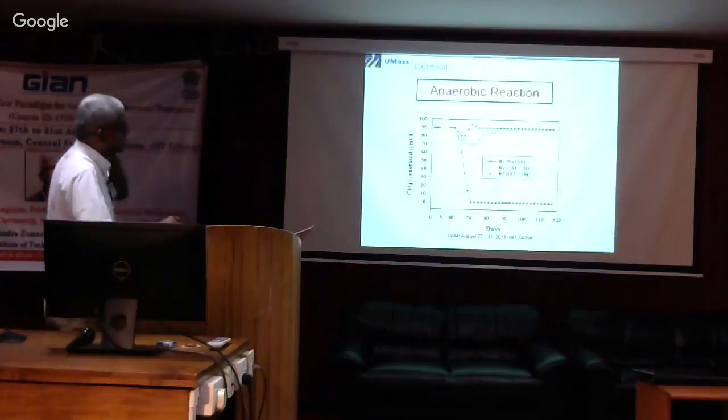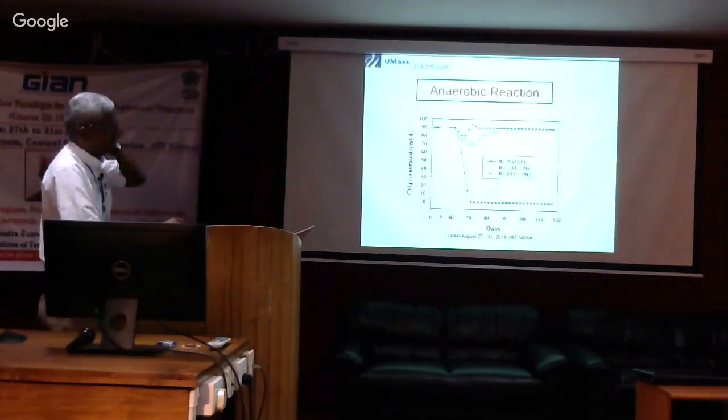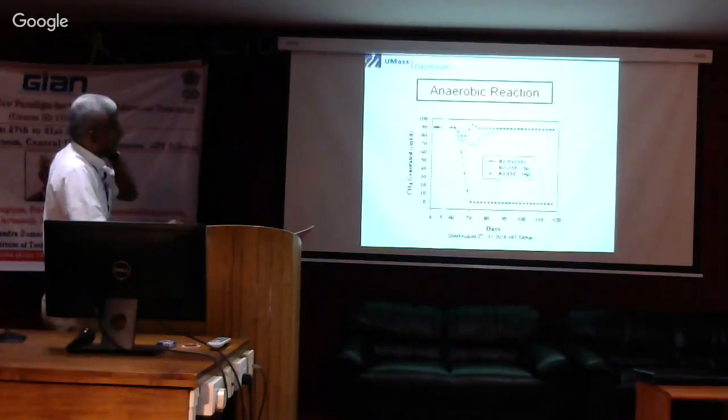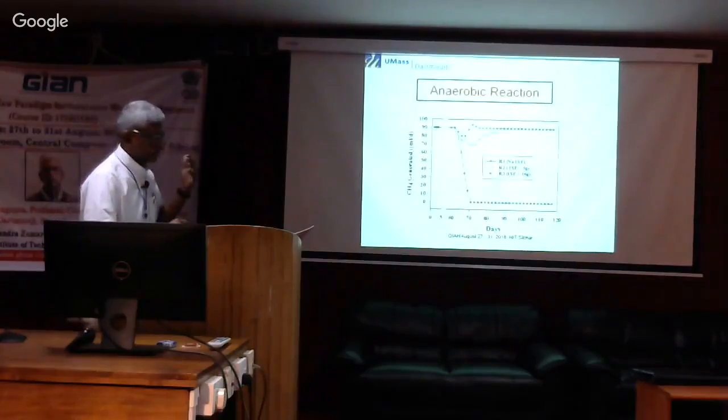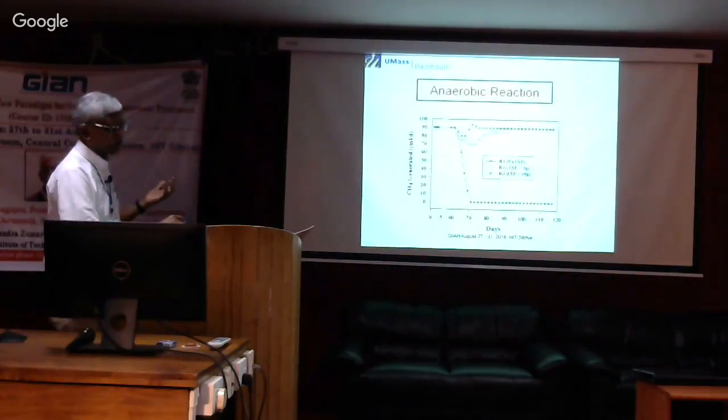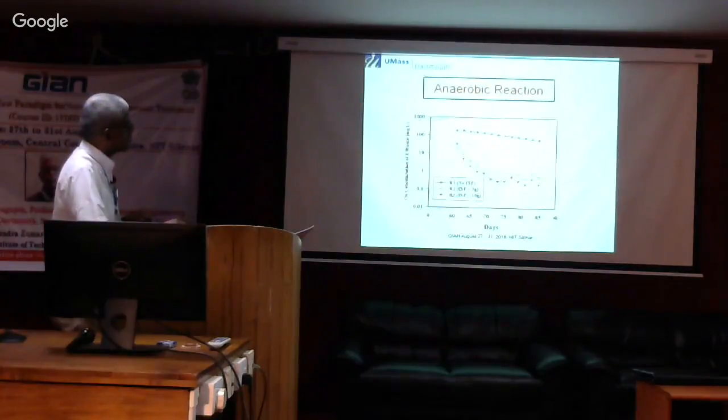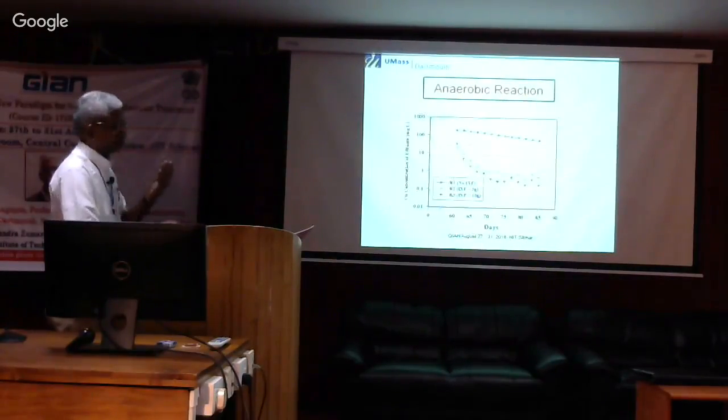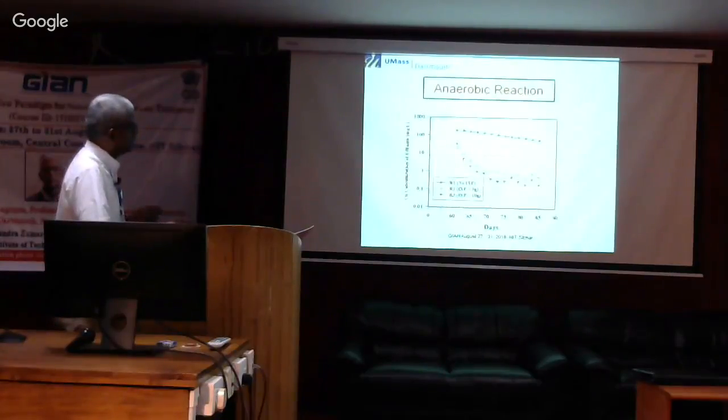So the point is that this kind of an approach where we are putting in a weak acid cation exchange fiber, it can absorb some of these shock loadings of toxic metals. And of course, the copper concentration, if you do not have any IXF, the copper concentration will go straight through in a way. Whereas if you do have the fiber, your copper concentration coming out would be much less.